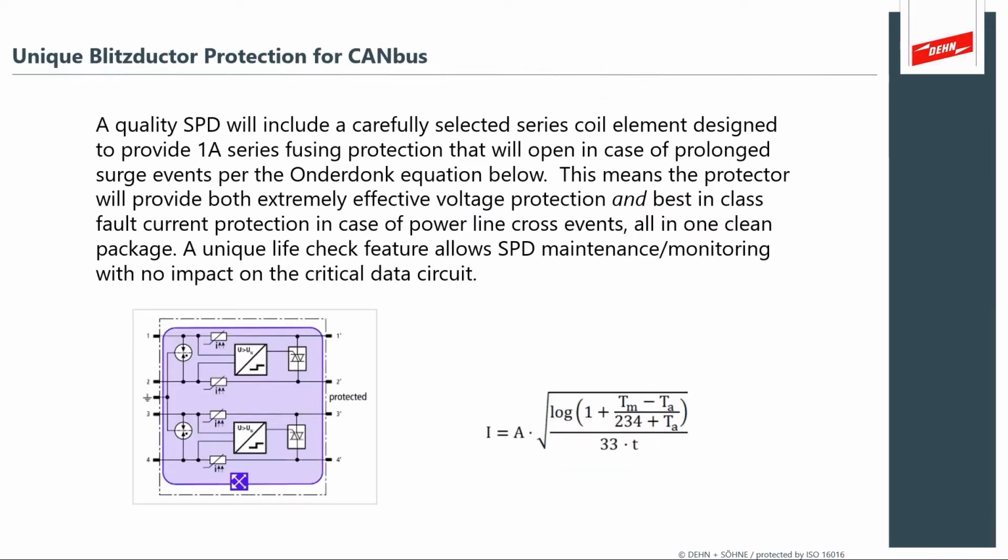So as we start talking about the actual surge protection methods, I wanted to take a moment to illustrate what the SPD, the surge protection device, is actually doing. You have an unprotected side where the circuit has exposed wiring, and you have a protected side coming into your marshalling cabinet where all of your control systems will be. And in this illustration, we can see a spark gap device, which is very robust, handling the incoming surge energy. It's controlling the voltage across the wires relative to earth.